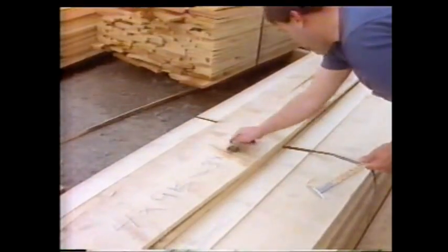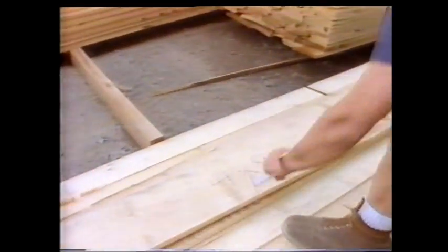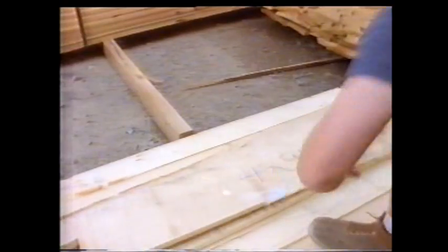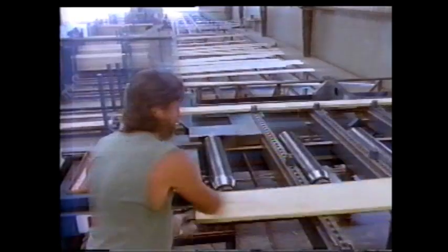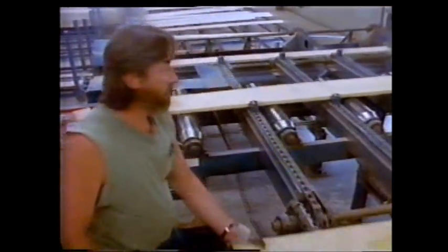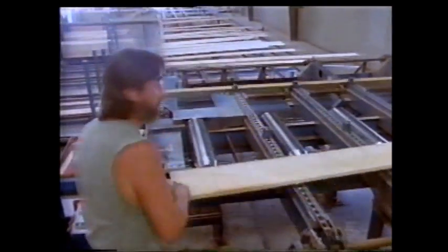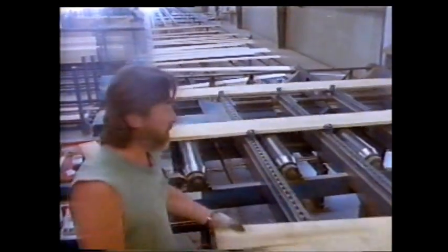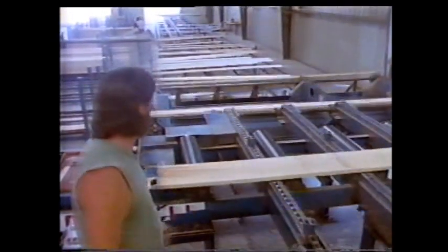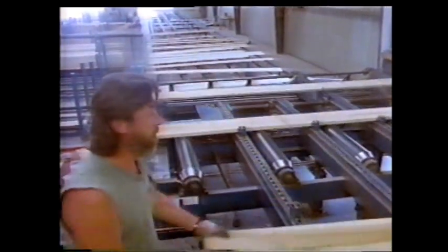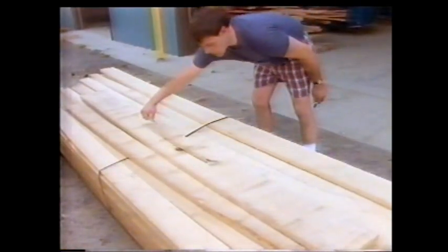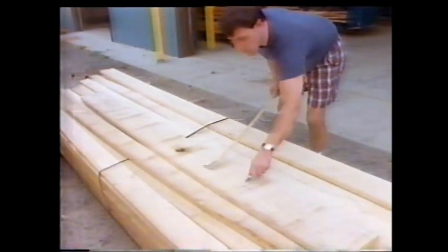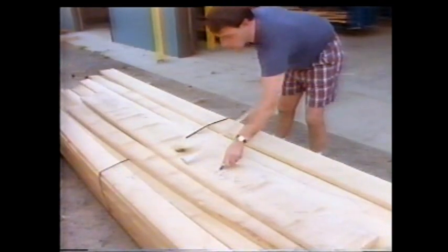Remember, boards aren't graded by their overall appearance. It is assumed that the user of the board wants clear lumber to work with, and so a piece of lumber is graded according to how much and what sizes of clear lumber can be obtained from any particular board. Since each grade demands a certain number of cuttings, the inspector will try to get that number out of the board. The inspector must also determine the minimum size of the clear face cuttings needed to maintain a trial grade.